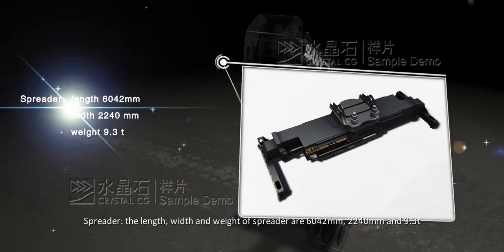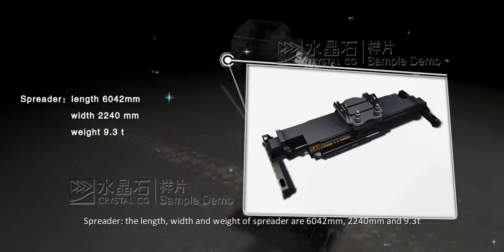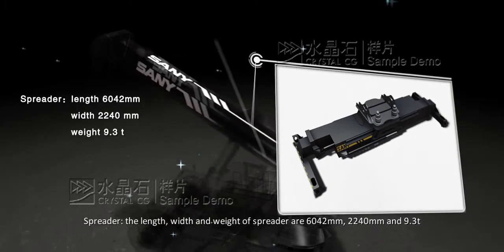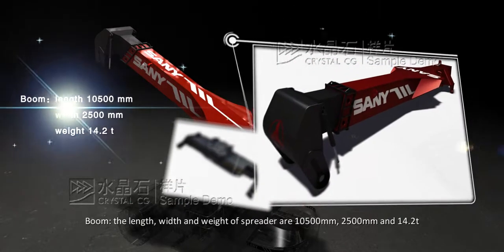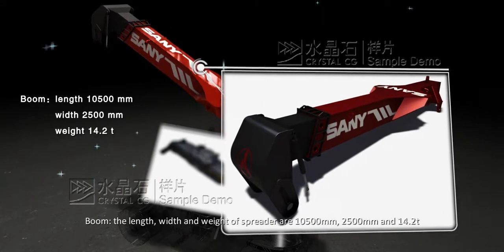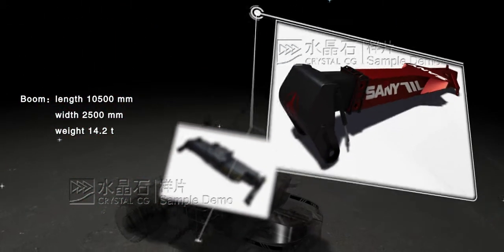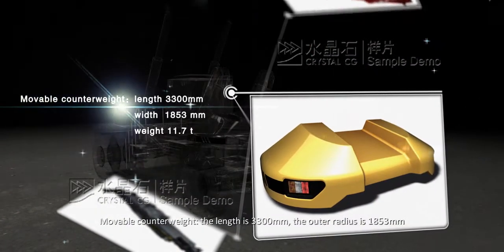Spreader. The length, width, and weight of spreader are 6,042 mm, 2,240 mm, and 9.3 tons. Boom. The length, width, and weight of boom are 10,500 mm, 2,500 mm, and 14.2 tons. Movable counterweight. The length is 3,300 mm.